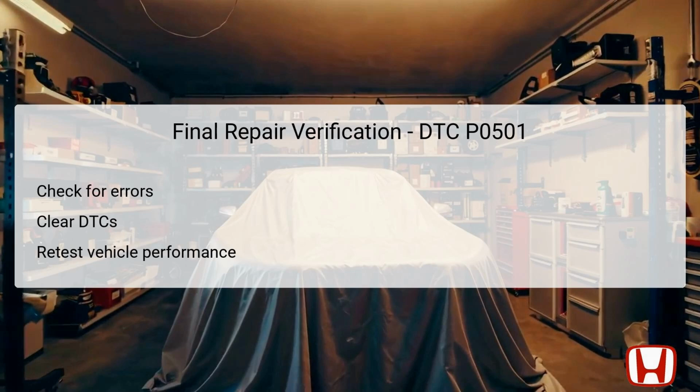It is advisable to retest the vehicle under the same conditions that initially triggered the DTC to accurately assess whether normal speed detection is restored. By verifying that the MIL light is off and there are no error messages, the repair can be deemed successful.